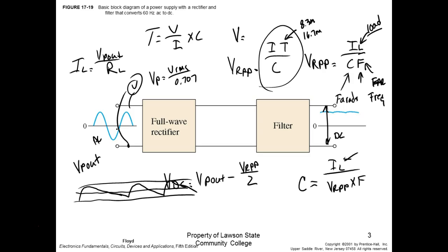So an open diode, which would make it really drop down, right? You understand. Could be an open diode, could be a shorted winding in your transformer. Or it could be you're just trying to pull too much current load. So instead of your load pulling 1 amp, now it's pulling 2 amps, which means that discharge, you designed it for 1 amp, you chose a capacitor for 1 amp, and now it's trying to provide what? 2 amps, and it's going to discharge that. So that means your load is trying to pull too much current. And that's hard to find, guys, without breaking the circuit and measuring.